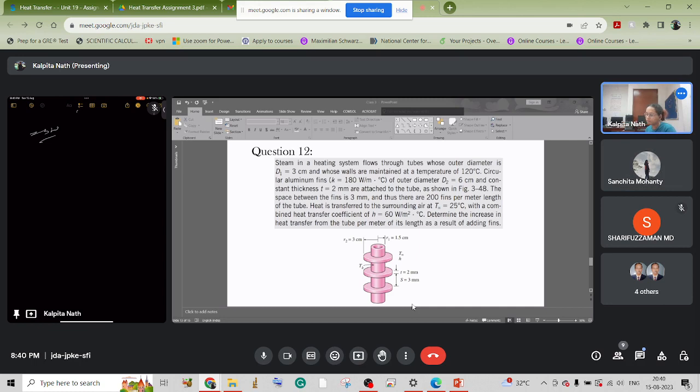No, it's wrong. It won't be 30.78. Ma'am, I will calculate it. Without fin, just wait 1 second. It will be area of no fin, that is when fin is not present. So I have just denoted it as no fin, nothing else. So it will be base temperature minus infinity. So base temperature is 120 and infinity, that is the ambient temperature, is 25.